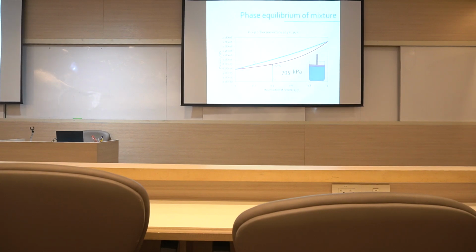Okay, let's find NV over NL at these conditions. NV over NL, that is the ratio of the number of moles in the vapor phase to the liquid phase, right? Then we actually see the answer here. It's all vapor, right? But we can still apply the lever rule here. The lever rule: NV over NL is A over B, right?